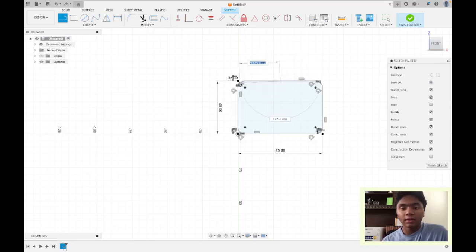If I move along the other edge right here and keep going on it, eventually, again, I'm going to hit that triangle. So that means I'm at the middle of that edge. Now, I'm not going to click on my cursor just yet because this would draw a diagonal line. Instead, I'm going to start moving my mouse towards the middle of the object, where as you can see, it's drawing a blue dotted line from the middle of that edge.